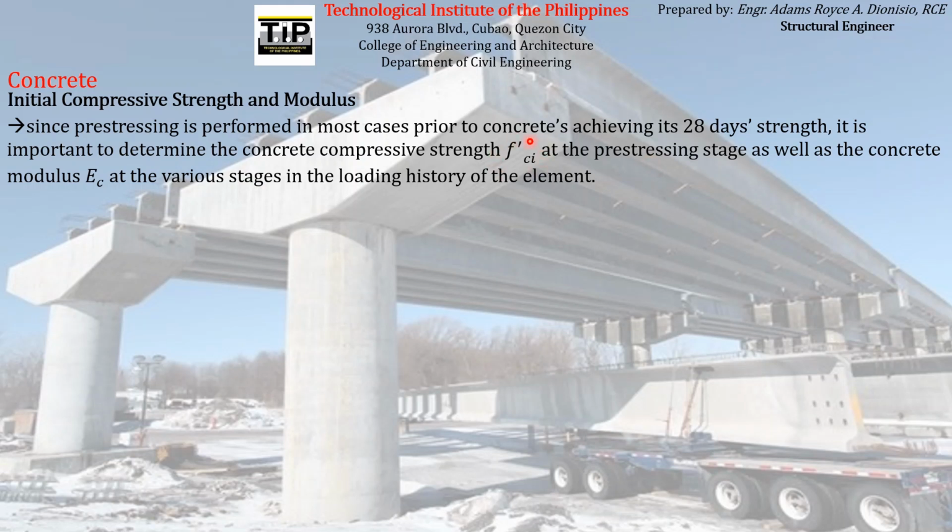So therefore, if they have different compressive strengths, they will have a different modulus of elasticity, because just like what I've said, modulus of elasticity is dependent on compressive strength. So it is important to take note of that different compressive strength at the time when the pre-stressing force from the pre-stressing reinforcement is transferred to the concrete element.